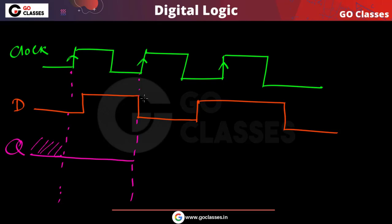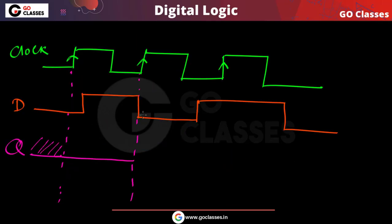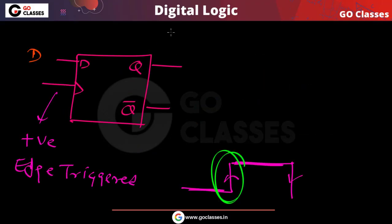Now here there is a problem, here there is an ambiguity, here there is a confusion. What is the confusion? We don't know whether this flip-flop is going to consider the value 0 or value 1. We don't know. Is this an ambiguity or no? So you can notice here the clock is going from 0 to 1, and at the same time the D input is also going from 1 to 0. So there is a problem. We don't know what this flip-flop will do.